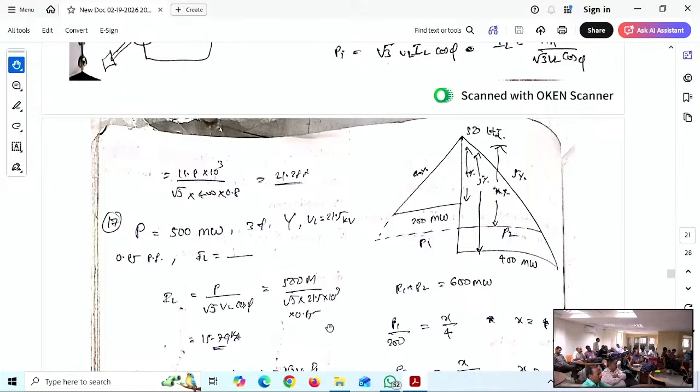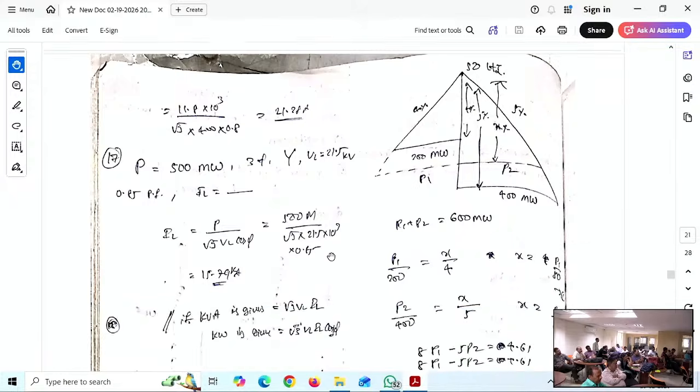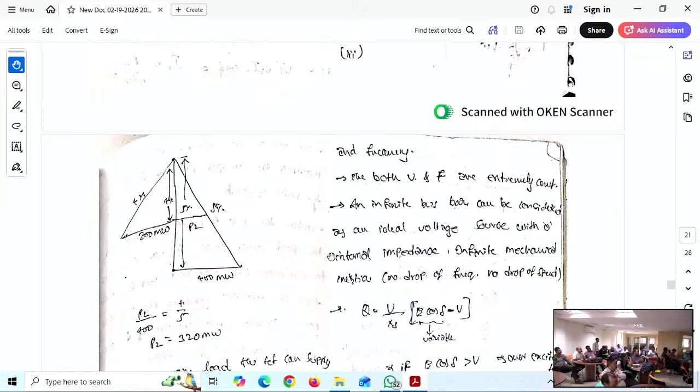Upon fixing this 200, now we draw the new drooping characteristics here. New drooping characteristic is this. We are fixing this 200 now because machine 1 can be fully loaded. Machine 2, P2, we do not know. It is the full load characteristic. Upon 400 giving 5% is the droop. Right. Now P2 is unknown. Now maths: P2 by 400, this ratio by this ratio is equal to this ratio by 4, okay, 4% by 5%, yes. We can do that. Now P2 is equal to 320.